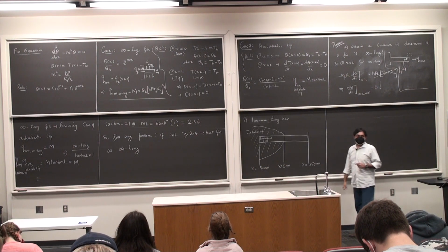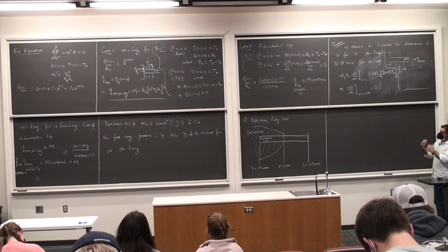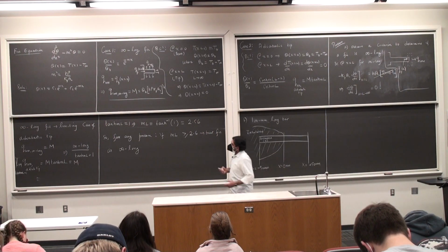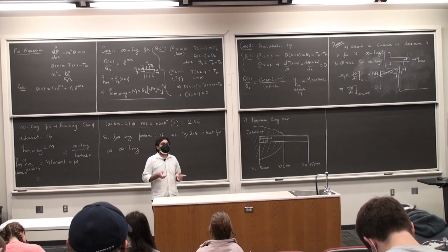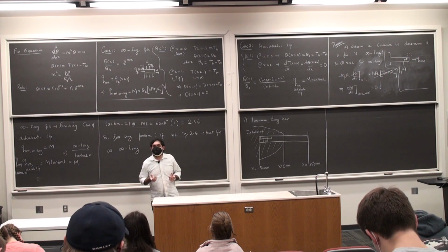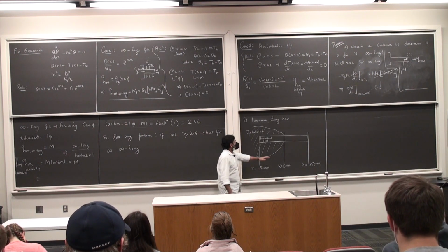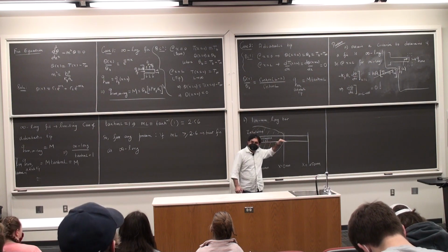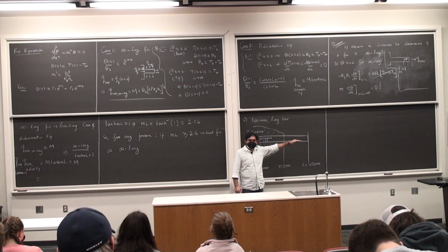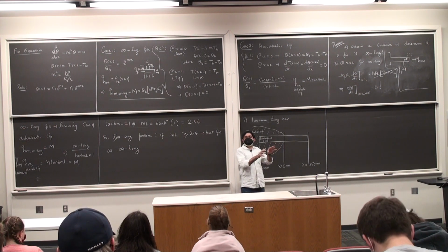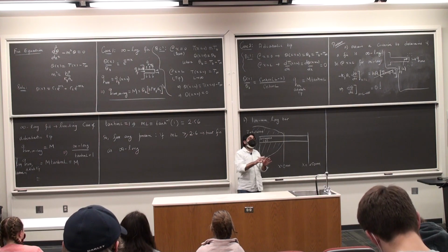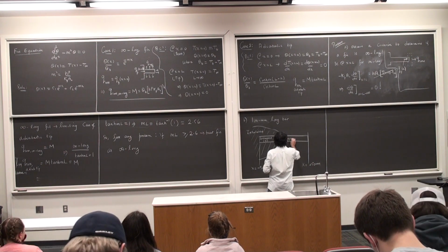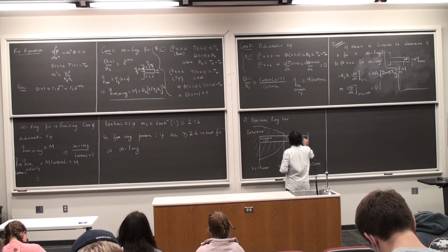I'm going to give it a subscript little e, okay? And then there is a portion that is protruding out from the wall. In the problem, they will not necessarily tell you that this is a fin. We have to figure out that this is a fin by thinking, okay, if this guy is sticking out, it's a solid body, the direction of conduction heat transfer is along the length of this protruding bar, but the direction of convection is perpendicular to it, which means that the portion that is protruding is actually a fin. Okay, so this is a protruding portion. This is a fin.